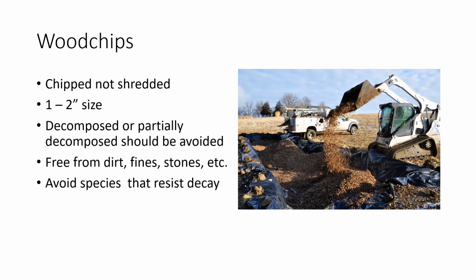So when we look at wood chips, what are we looking for? It's very important that you know your source of wood chips beforehand, and if it's an NRCS project, or any project, that the source meets your approval before they come to the site. Nothing's worse than having your contractors there with the pit open, ready to go, and then the wood chips show up and they're not the right type of wood chips, or it's just not the right material, and you have to turn that semi-load of chips back. It just puts everybody behind schedule.